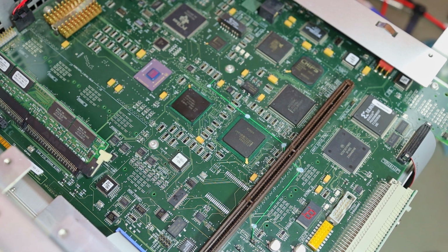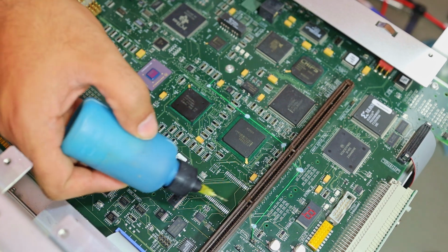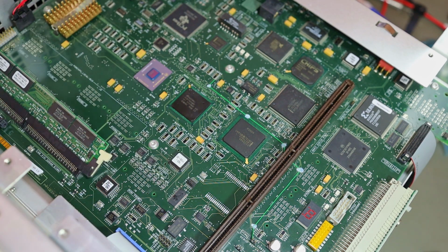There is some solder left. I will do the same work one more time, because I do not have a microscope. I cannot check, and that's why I have to redo it one more time. I will use my wick and try to clean everything. Maybe increase the temperature by 5 degrees.